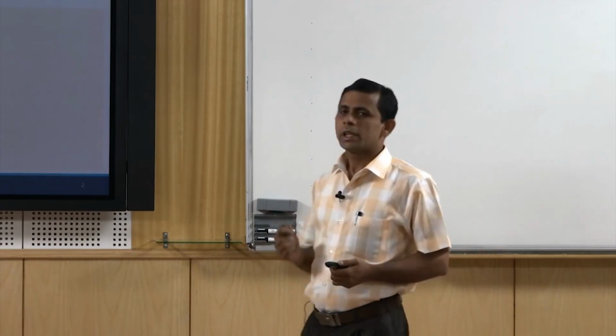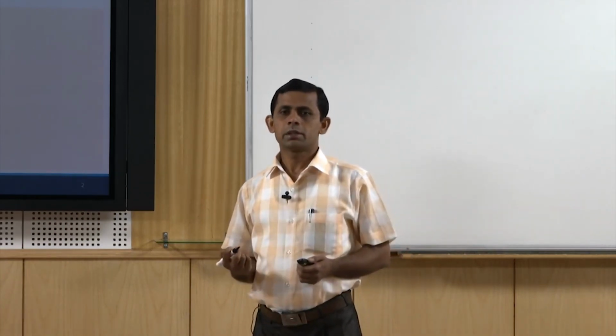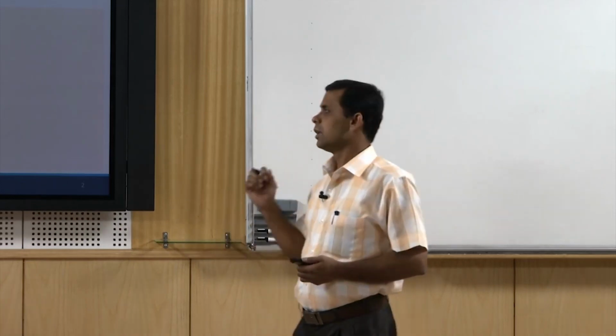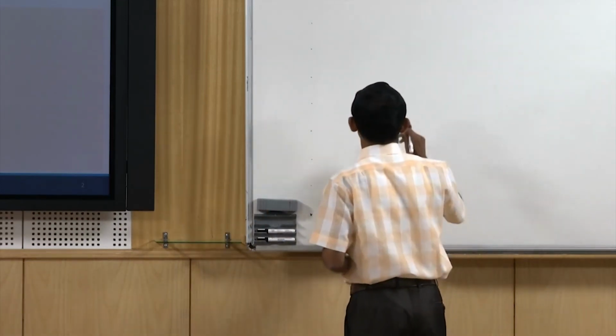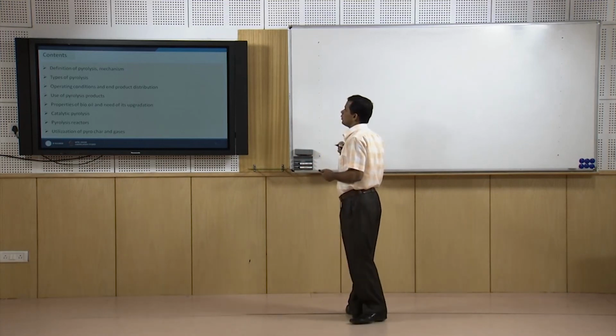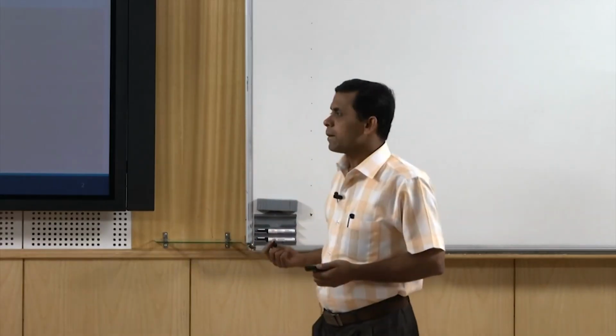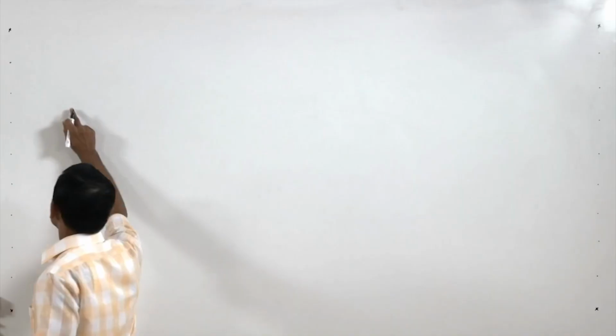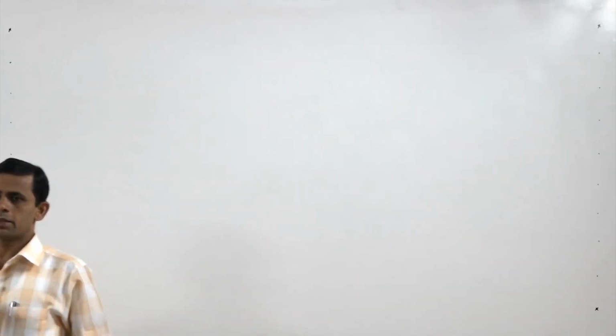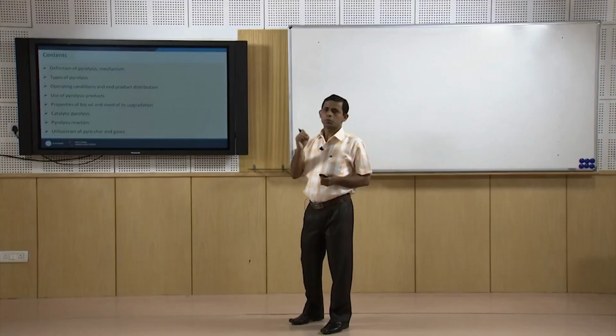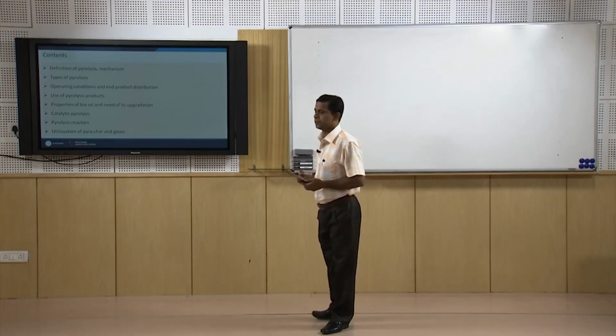This pyrolysis process is not widely used on a commercial scale, but extensive research is going on for its development, and so in future we may get commercial scale applications of pyrolysis. In incineration, we use an excess amount of oxygen, in gasification we use a controlled amount of oxygen, and in pyrolysis we use no oxygen theoretically, but some amount of oxygen may be allowed and some new research is going on. So, pyrolysis in the presence of a smaller amount of oxygen.